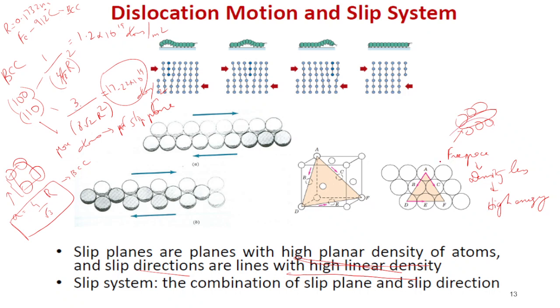So this will cause heavy dislocation along the grain boundaries. And not only that, there should also be cross slip. Cross slip means slip of one grain should coincide with the slip of the other grain, so that they will all come together and result in the failure of the material. In case cross slip does not occur, in that case the material will be strong.